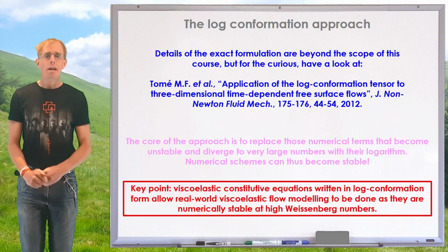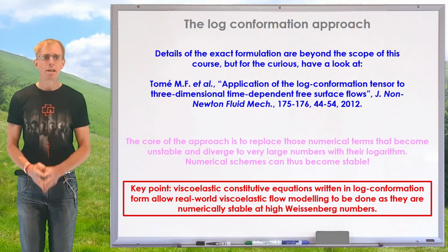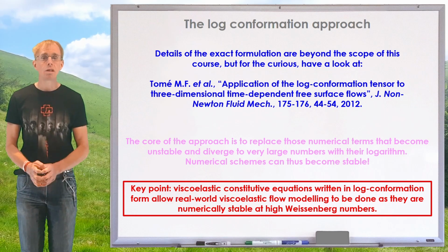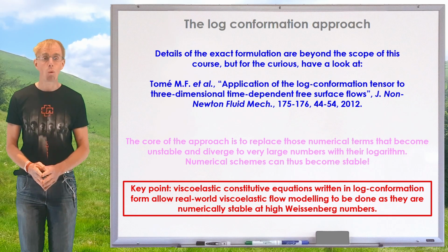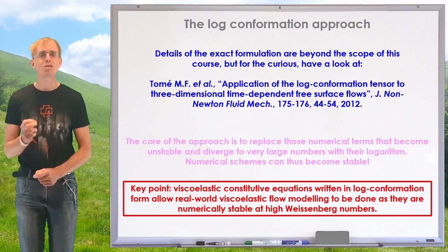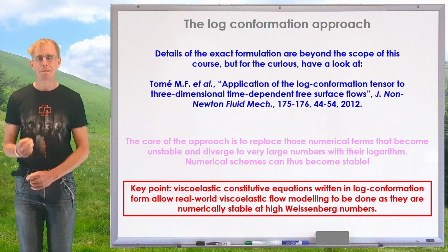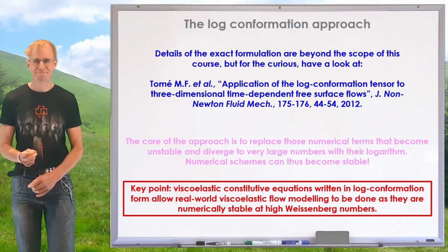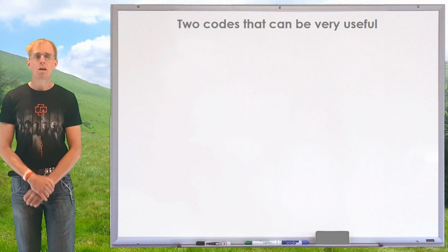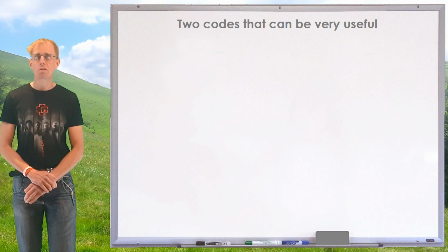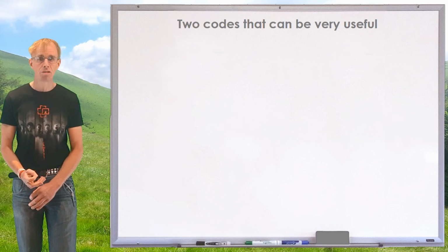So if you're dead set on doing flow modelling for viscoelastic liquids in engineering type geometries, you're going to need to use, in all likelihood, log-conformation methods to do it. Or more realistically, you're going to need to choose an existing code that already has log-conformation methods implemented within it. Since we're talking about codes, there are two codes that you might find very, very useful. I'm not going to go into any more detail other than a brief overview to alert you of their existence.